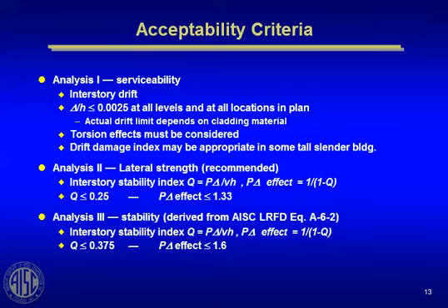It limits the Q value. And we've got our own practice. Steel doesn't have that same explicit limitation now in the 2005 spec, but we have our own. We say under the factored gravity loads that we're going to limit that Q value to 0.375, which means we're limiting the P delta effect to 1.6.